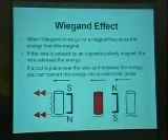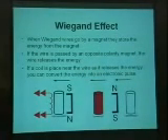That's what a card looks like. That's what it looks like when you hold it up to the light, so you can clearly see the wires embedded in the card. And basically, what the Wiegand effect is: when you wave your special bit of Wiegand wire past a magnet which is polarized in a particular direction, it charges up with magnetic field.